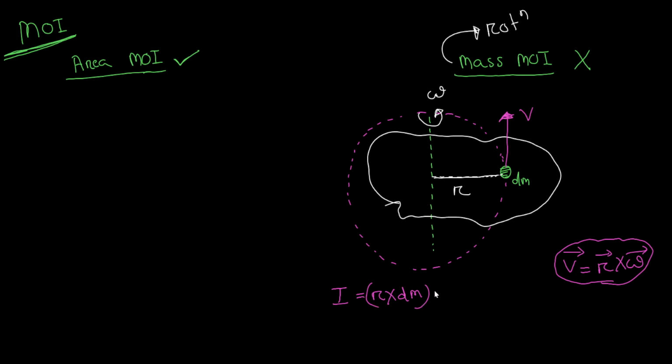Again we have to calculate with another radius. So the second time, twice we have to take the moment of the mass. That will give rise to the mass moment of inertia. So I will write r square dm for the small mass.